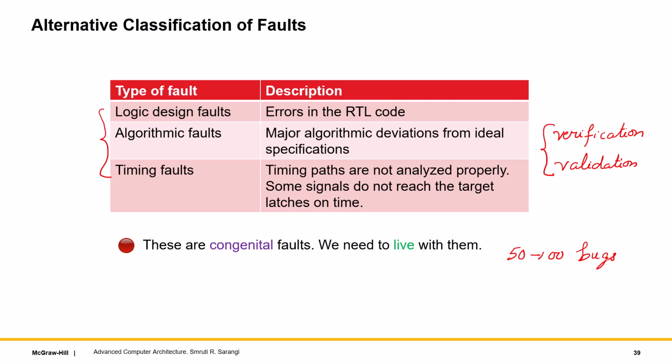So all of this is dutifully and very meticulously documented in the errata documents. Some bugs are serious, but perhaps not that serious to recall the processor. But bugs still happen, and a lot of BIOS and firmware developers, where a large part of the firmware is within the BIOS, and OS developers plus compiler developers actually read these errata documents and try to generate code to avoid these bugs.